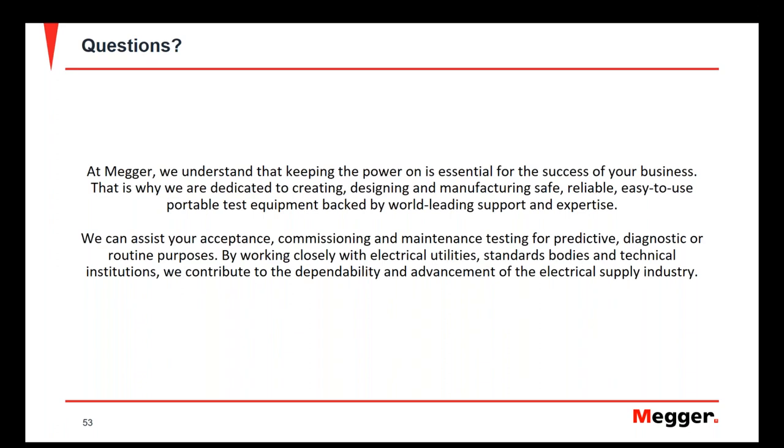Thank you, Volney. Next over to Sanket. Sanket, why can't circuit breaker test sets be used to test reclosers? Yeah, so when Jason was covering the products, he mentioned that the OCR 15D or 50D is what we use to test oil circuit reclosers.